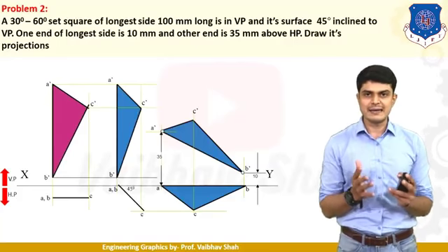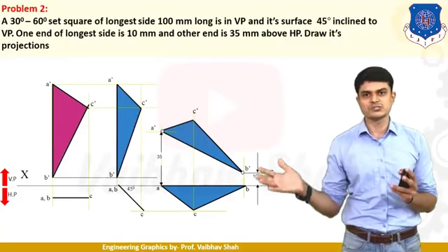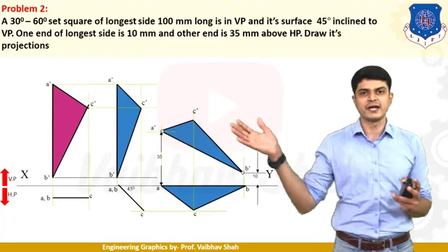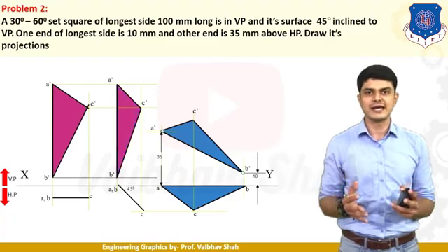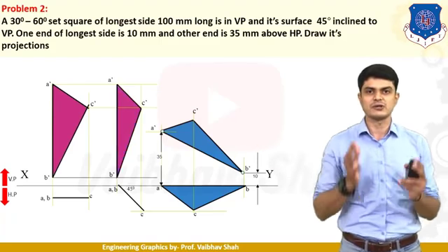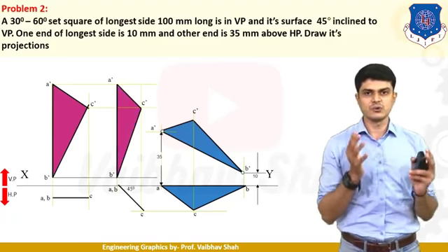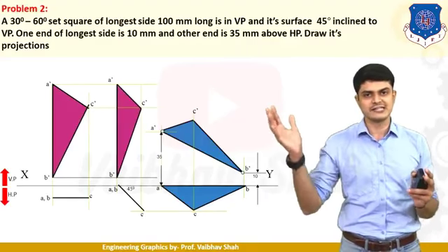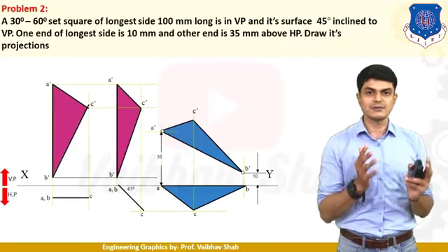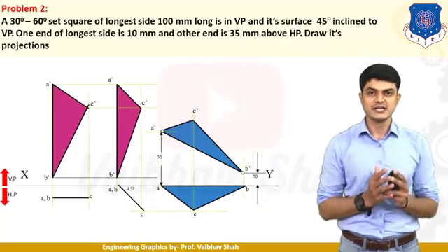After drawing this line ABC at 45 degree incline, you must draw the vertical lines from each and every point and horizontal lines from the previous triangle. You will have the second stage triangle drawn like this. Give the notation A dash, B dash and C dash. So now let us come to the final and interesting stage.